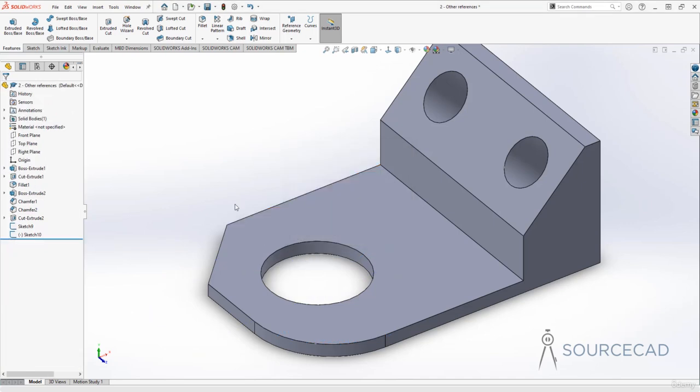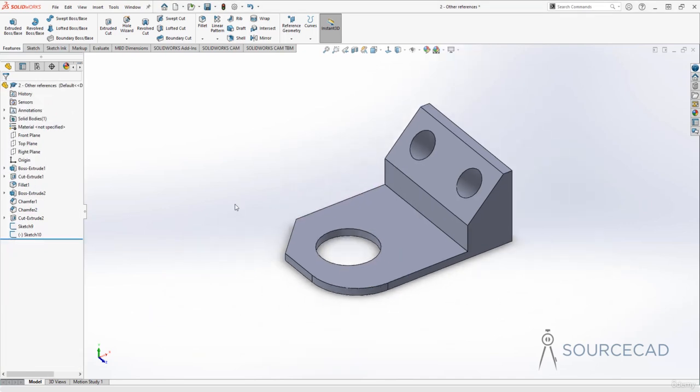Now finally let's talk about creating coordinate system, and you can create coordinate systems using this option right here. Now we already have a basic coordinate system here which is the default one, but if you just want another one for maybe let's say CNC machining, and you just want to specify a different coordinate system with respect to your selected part, or maybe you want to specify several different coordinate systems for several different features of your drawing, then you can do that using this coordinate system.